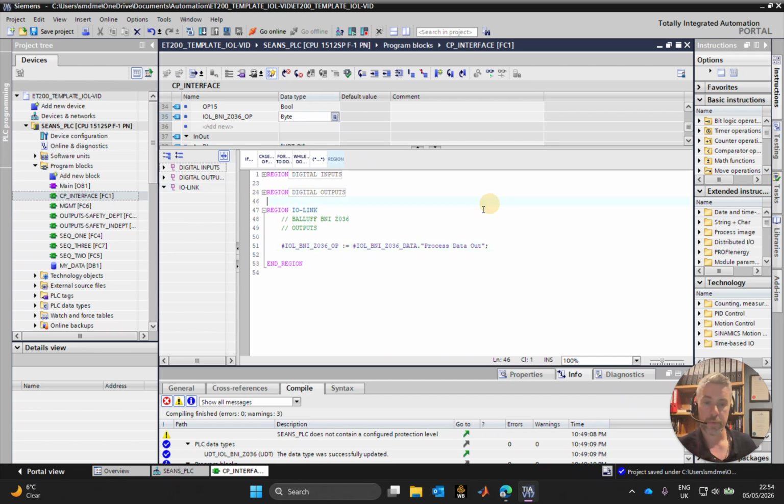That's it. Done. So now I have an association here between the physical space, the 24 volts or no 24 volts going out on 10.0, 10.1, 10.2, 10.3, and so on. That is now going to be 1's and 0's in accordance to what I code on my PLC to be 1's and 0's, and what's going to be stored in my data block. All right, so there's the IO link.